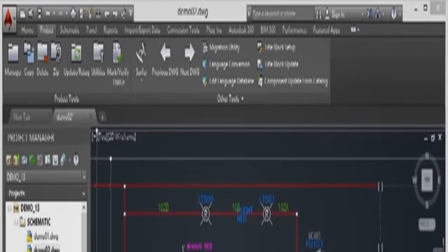Now, we've mentioned Scoot before, but you can also scoot components as well. So let's zoom in on this top left area of Drawing Demo 02. And let's have a look now at scooting a component in an AutoCAD electrical drawing. Now we've got a light down here, which is our power on light that came off of one of the panel drawings previously. What we want to do is scoot this along to the left, so it's here on this part of the wire length over here on the left-hand side rather than over here on the right-hand side.